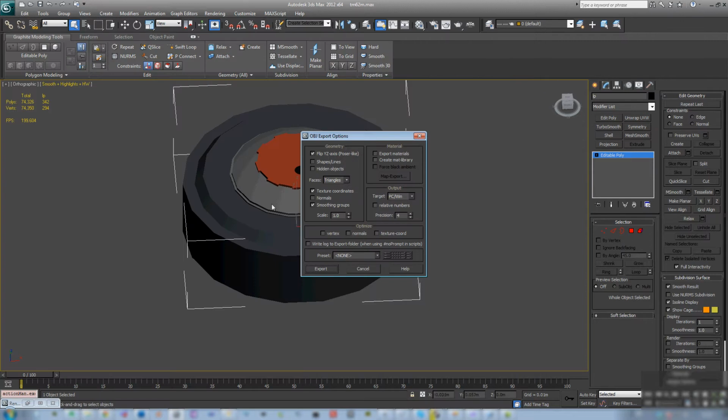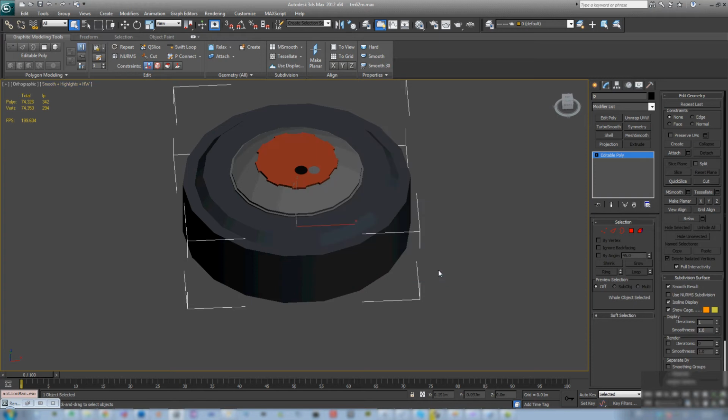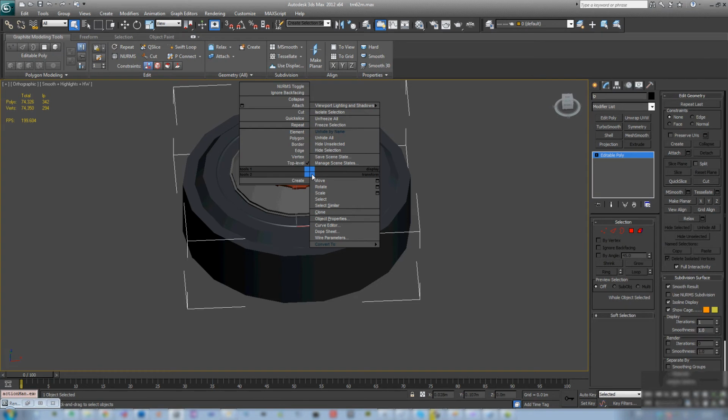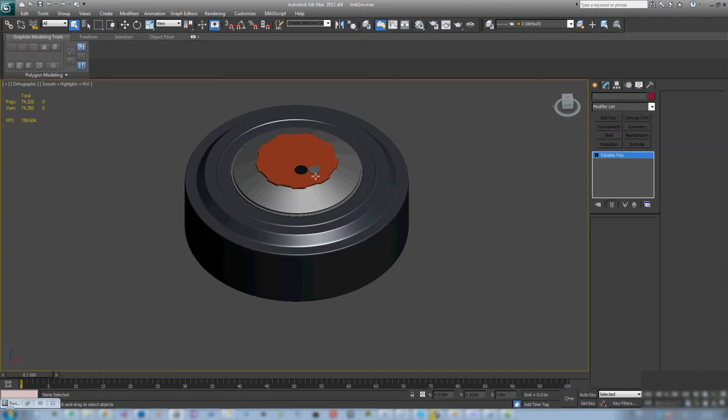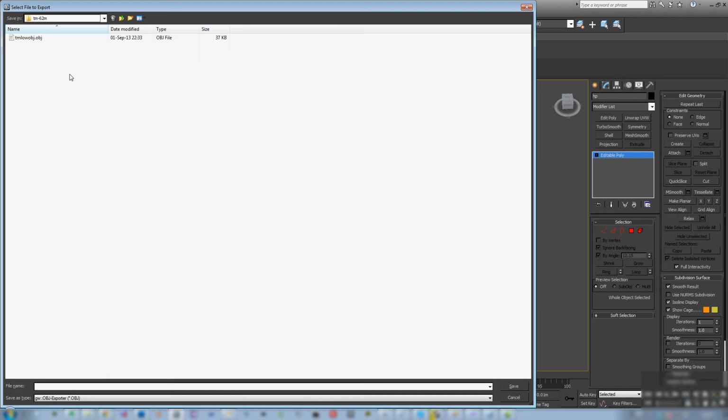Save. And important in the settings, just keep an eye on what I'm doing here. All the settings keep them the same. Uncheck normals because DDO will mess up the triangulation. So okay, so we hide the low poly now. Unhide the high poly. Make sure it's also one object, so whatever your model is, make sure it's just one mesh, one editable poly. And do the same thing.